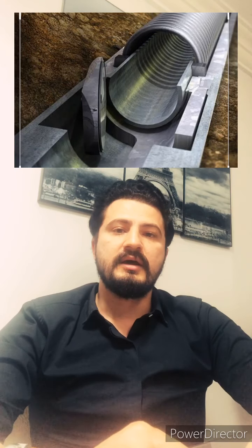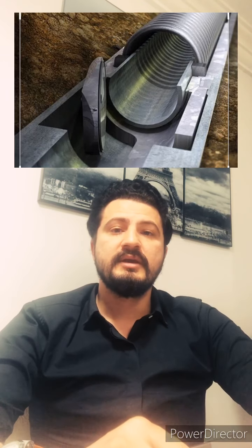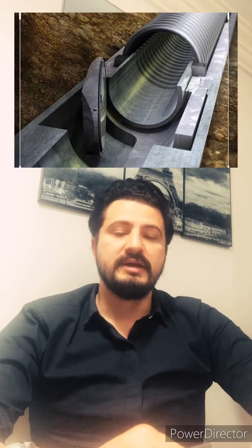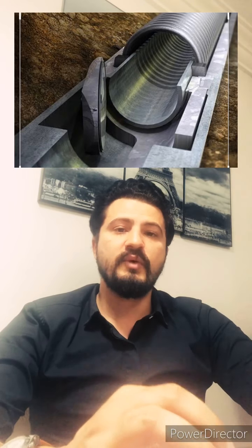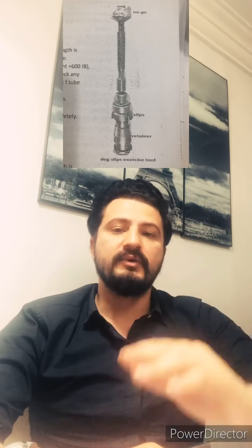So, when the flow tube is stuck, which is one of the most common problems in a tubing retrievable safety valve, stuck here means it couldn't move up or down completely. In this case, an exercise job will be the first solution: any try to catch the flow tube to move it up or down mechanically by standard wireline equipment. If this trial or exercise job does not succeed, we go to the next step.